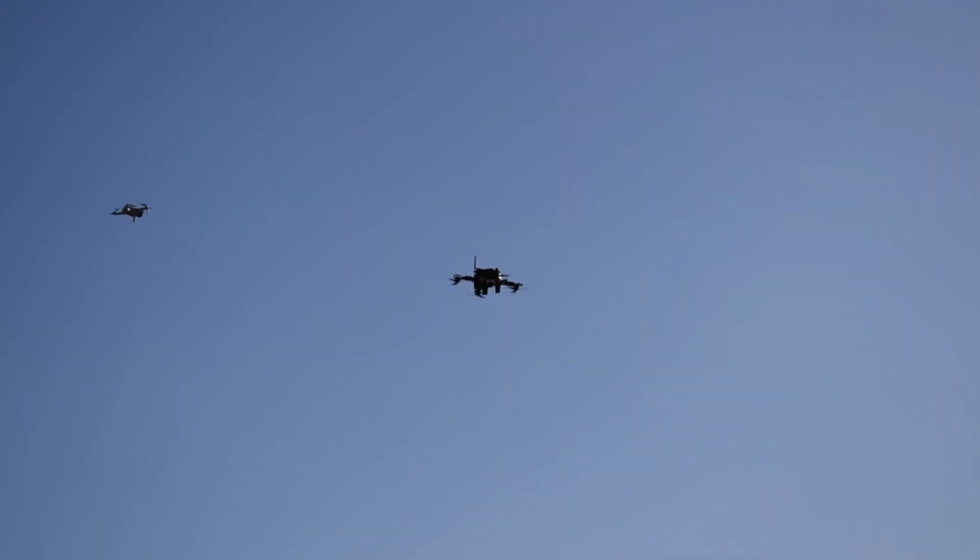In order to test our obstacle avoidance on the drone, we've flown our drone up into the air and flown other smaller drones nearby in order to see if our sonars would pick up the detection of those objects. We can monitor that through our ground station, and we've tested and made sure that our sonars do work and do detect other objects in the air. We've also tested the off-board functions that we'll be using on the drone, which move the drone a certain distance in a certain direction, and we can use these functions in order to move the drone away from whatever object may be in the air.